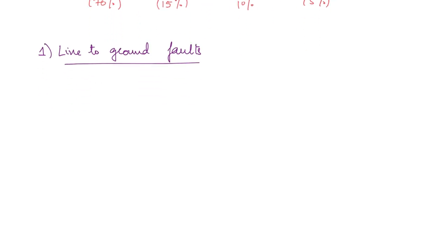So if you take the three lines, let us say these are the three transmission lines, and the fault has occurred somewhere here. Now when fault occurs, it is a line to ground fault. So you can take this as a short circuit or even a fault impedance. If there is no fault impedance, simply ZF will be 0. Now the current through the other two phases is going to be 0 because all of the current will now flow through the fault because it is offering a short circuit path, right? So all of the current will now flow through here.